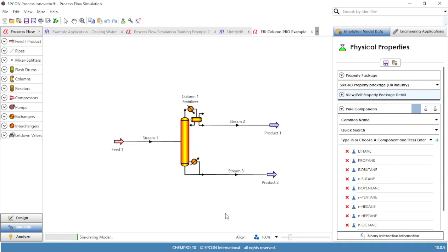And that will do the theoretical calculations plus the hydraulic calculations for each tray or packing, of each stage. That will then be passed back to the theoretical column calculation as the more accurate pressure drop, and that loop converges until they match. So the end result is you automatically calculate the pressure drop for each stage for tray or packing, and that matches your theoretical columns calculations to rate the column or to analyze it for performance problems.